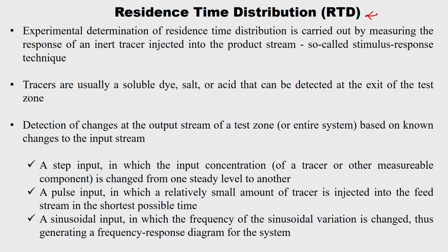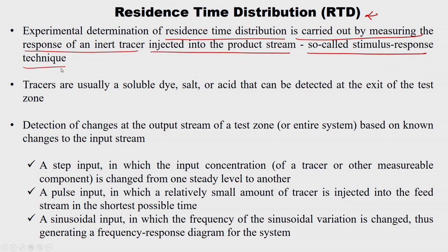The experimental determination of residence time distribution is carried out by measuring the response of an inert tracer injected into the product stream, the so-called stimulus response technique. How do I understand this? I cannot directly do anything in the product. So, I will introduce the tracer and trace it to find out how much time it spends inside the heating tube. So, this system is called stimulus response.